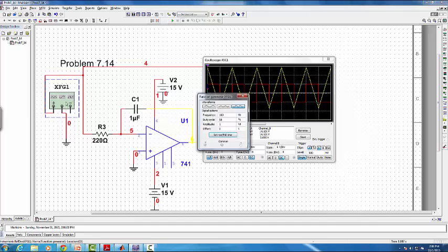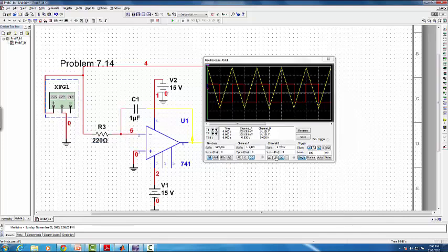So now I'm driving this circuit with a step function, because if you integrate a step function you should get a ramp function, correct? So that's what I'm driving it with. My input right here is this step function that's going back and forth between 1 volt and minus 1 volt. But truly, when I see a plus 1 volt input, because this is an inverting configuration, I have a negative ramp. And vice versa, when the negative input is in here, I have a positive ramp. So that's an integrator circuit behaving as an integrator.